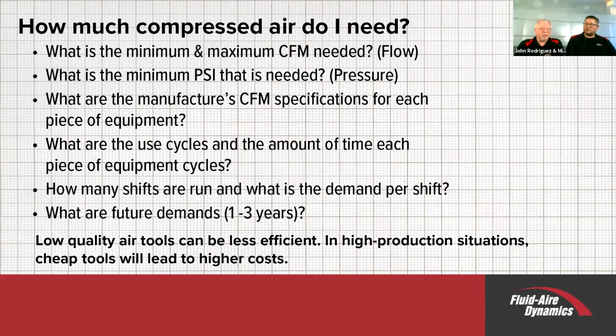Well, it's not necessarily the cost of the tool. Not only that, the better tool will last longer, but it's not only the cost of the tool you're looking at, but your cost of running that tool. So it uses twice the amount of air. An additional 5 CFM is at least a horsepower or so. So you have a situation here where you have to watch for inefficiencies in the pieces of equipment you're buying. Move on from there.